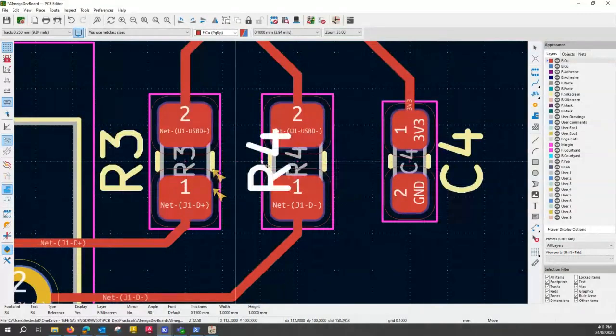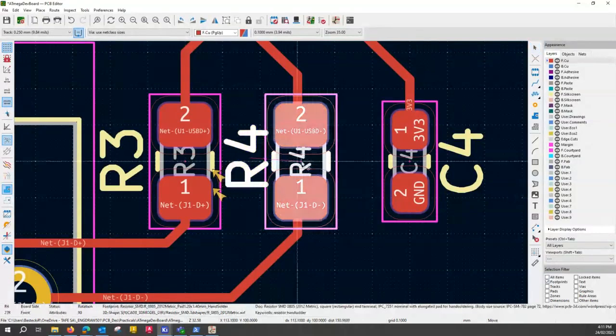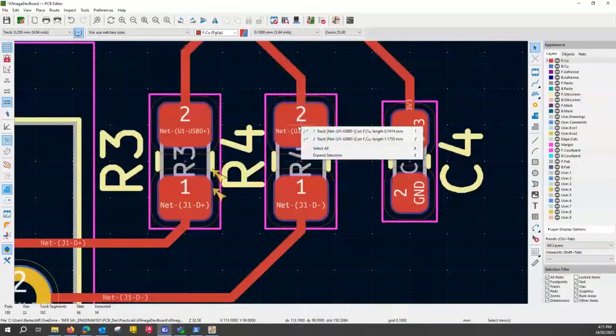Oh, look. We don't have a lot of space here. I can actually move a component. So what I'll do is I'll select that footprint, and I'll just move it out a little bit just to make sure that we've got enough space for our text. Select all components, text. The clearance should be okay. If it's not okay, we'll move it further. I can now fix my connections there. Now there's a little track there which we don't need, so I can delete that one and that one there.